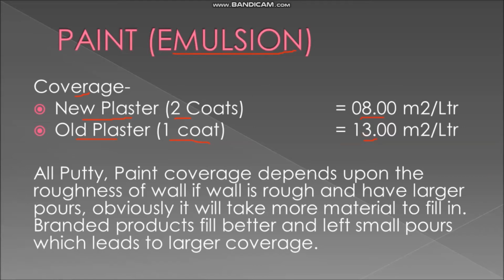Now I have to say that all putty and paint coverage depends upon the roughness of the wall. If the wall is rough and has bigger and larger pores, obviously it will take more material to fill in. Branded products fill better and leave small pores, which leads to larger coverage.